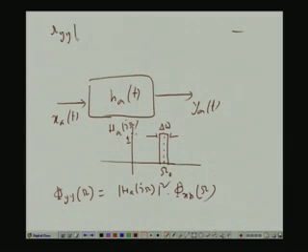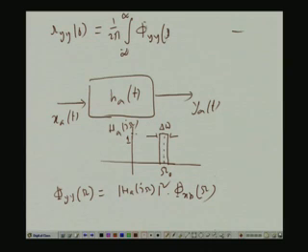Now, what is R y y 0, that is autocorrelation at lag 0? We have seen that this is given by 1 by 2 pi integral from minus infinity to infinity of phi y y omega d omega. In fact, that is why this is called power spectral density. Quickly, just to recall how it comes, we have seen that power spectral density is the Fourier transform of autocorrelation function. So, therefore, the correlation function here is the inverse Fourier transform of power spectral density. So, if in the inverse Fourier transform R y y tau, you put tau equal to 0, then e to the power 0 is 1. So, you get this integral only, which shows that the average power R y y 0 of the process is given by the integral, that is the area under the power spectral density.